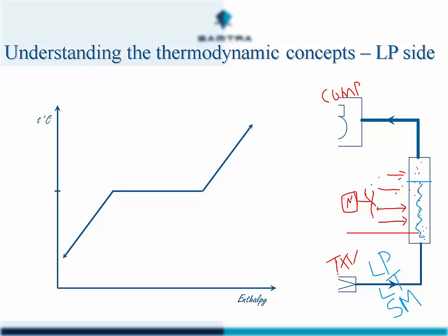And once we have this very cold refrigerant that's turned into a very cold vapor, the vapor is cold enough, it still will absorb heat energy. So the vapor will tend to warm up as it passes through the last part of the evaporator. This will then be a certain amount of superheating. The refrigerant vapor will leave as a superheated vapor. Low pressure, we're still on the low pressure side. We're still on the low temperature side, but now we have a superheated vapor.